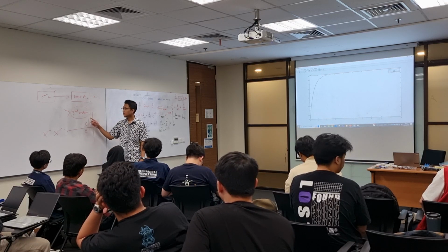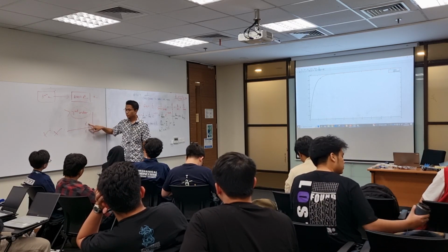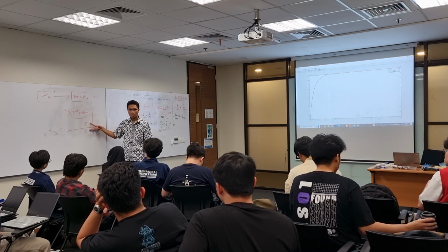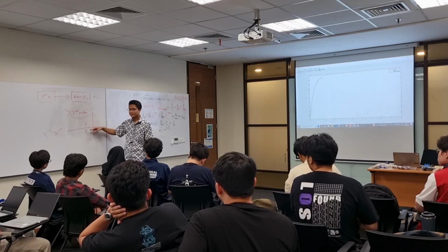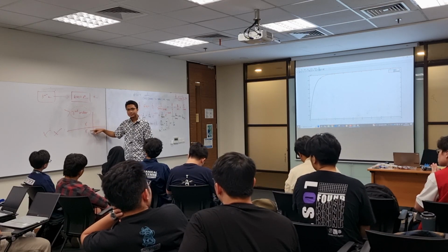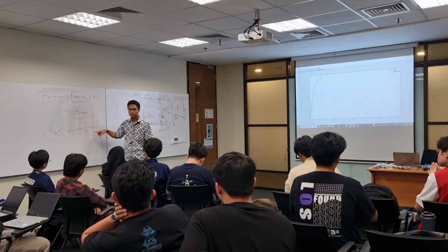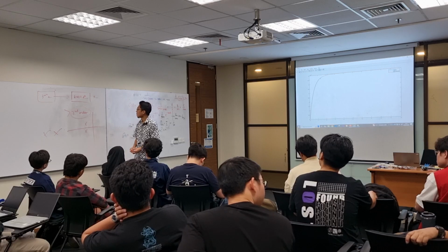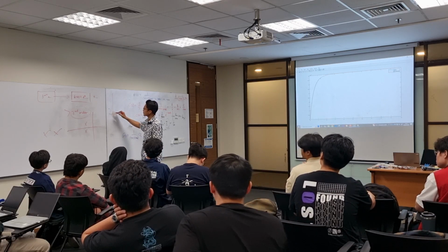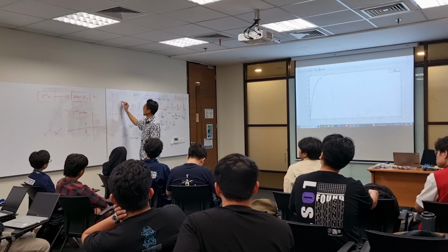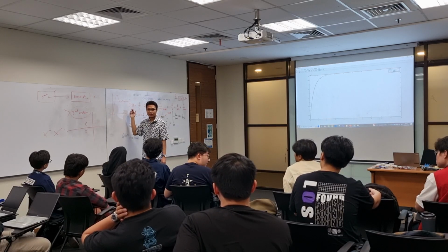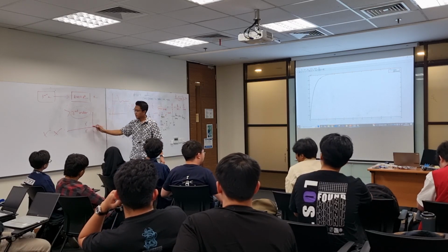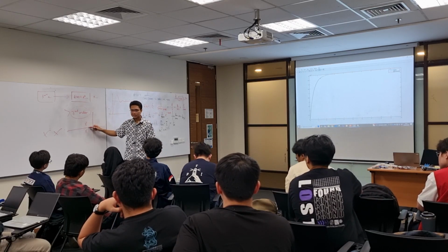Dominant pole only one? No. If it is second order, you have two, right? A second order system like this, it's two. Is a second order system the one that has damping? It's two, maximum two. You still remember the time domain measures? Maximum overshoot, rise time, settling time. These are defined by the complex poles like this. You see?